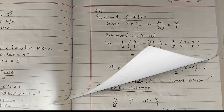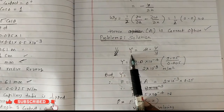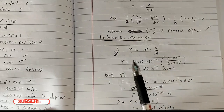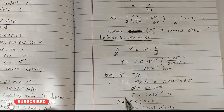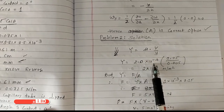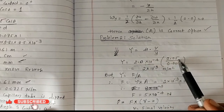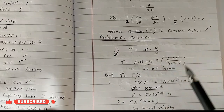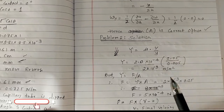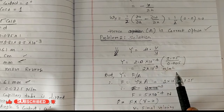Then we'll move to problem number 2. The solution goes like this way. We know that shear stress is equal to dynamic viscosity into velocity gradient. So tau is equal to mu into V upon h. So tau is equal to mu, that is 2 into 10 raised to minus 4, which is dynamic viscosity here. V is 0.05 because 5 centimeter per second, so that is 0.05, and the thickness is 5 millimeters, so therefore it is 0.005. So shear stress is equal to 2 into 10 raised to minus 3 Newton per meter square.